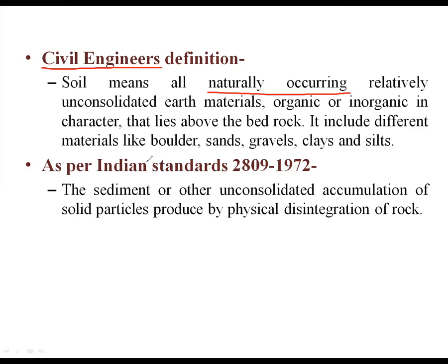For example, getting river sand nowadays is the most difficult part. So the sand we use in general construction is artificial sand. Artificial sand is angular, the grains are angular, so it blocks itself and does not provide proper workability to the concrete.